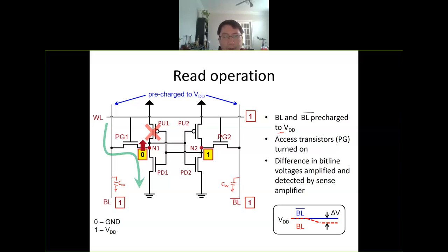So it's like a metal wire, isolation, metal wire. So this is like a cap. So you have the parasitic capacitance of the bit line. So the bit line actually is more like a capacitor, with a wire capacitance CW here, or CBL. So we need to pre-charge this cap of this bit line to be VDD, and also the bit line bar to be VDD.